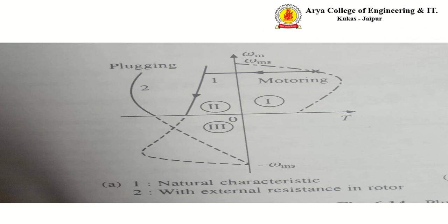If the supply terminal is changed, then the supply current direction also changes, so the induced EMF direction changes and the generating torque direction also changes. When the torque direction changes, the net torque reduces, and then the motor speed reduces.